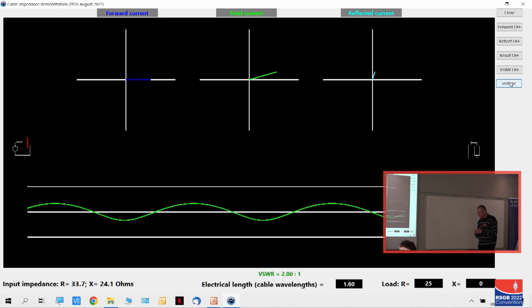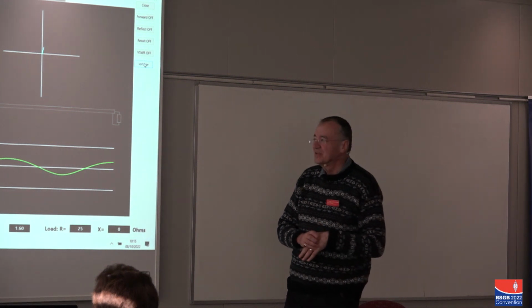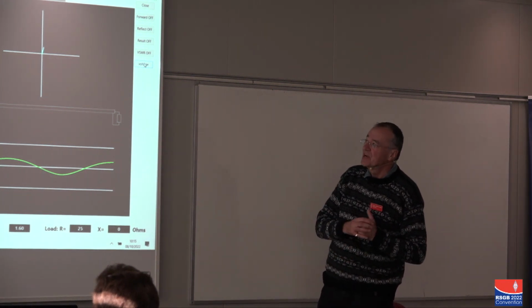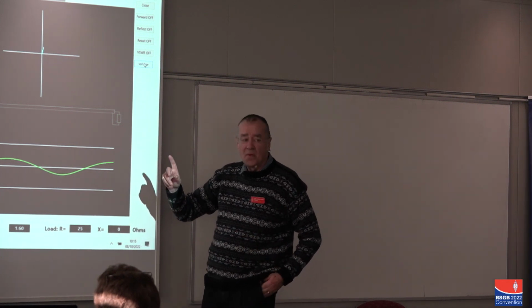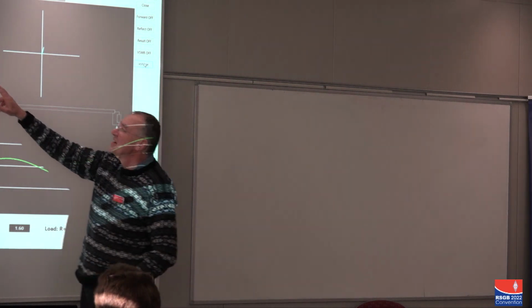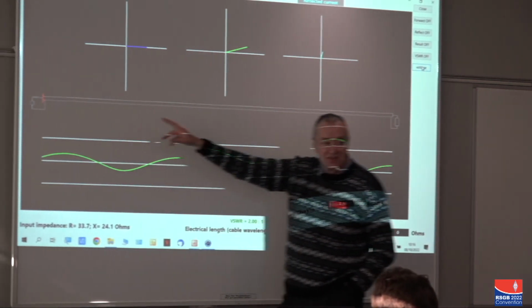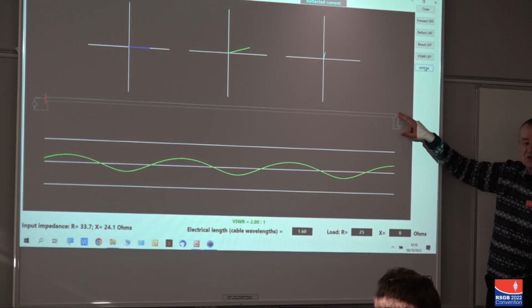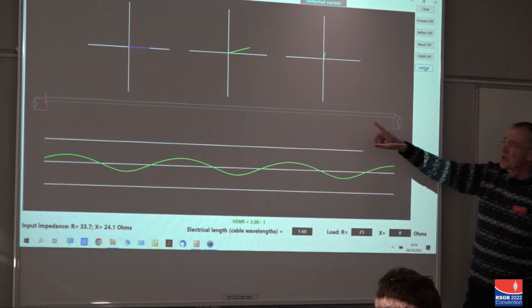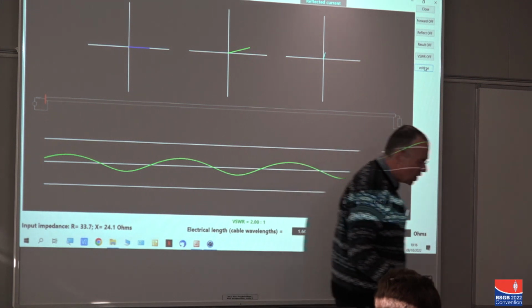Now, I'm not going to go into the intricacies of how you do a division on this phasor diagram. It's a pain, but what I can do is to point out one or two interesting things. The first thing is that obviously the ratio of the amplitudes and the phases at this point depends upon how much reflected stuff there was. So therefore it depends upon what your load is. Change the load, you're going to change the ratio, you're going to change therefore the impedance at the beginning.